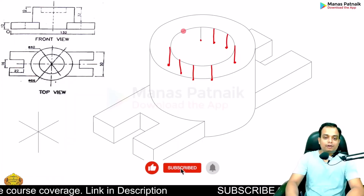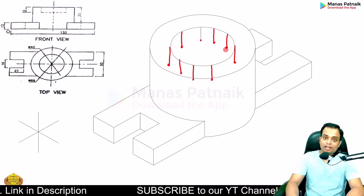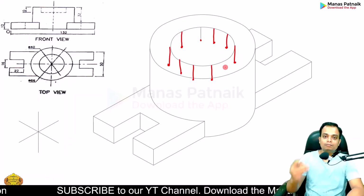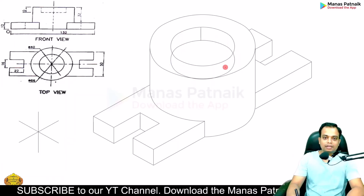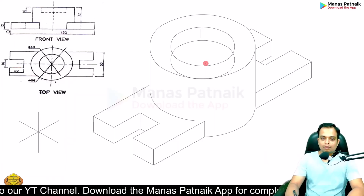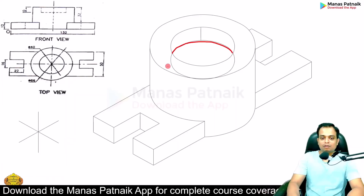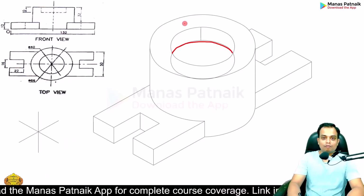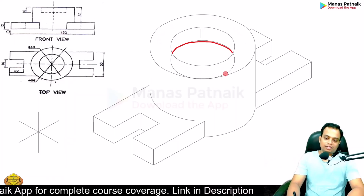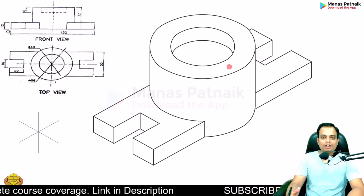You simply need to make points and not draw lines. Simply mark these points. And once you have got enough points, and once you're confident that you can pass a smooth curve through all of them, pass it. What do you think? Is this the final view? No. Only this much portion will be remaining, whereas this portion won't be seen as it is falling below this place over here. So let me get rid of it, and this is what remains. That's the final isometric drawing.